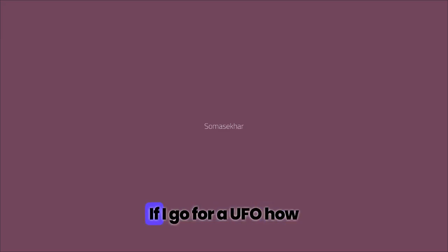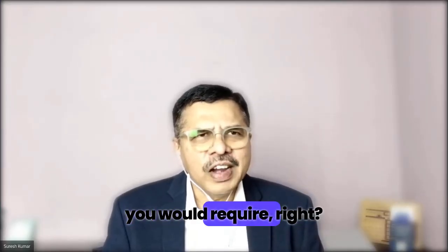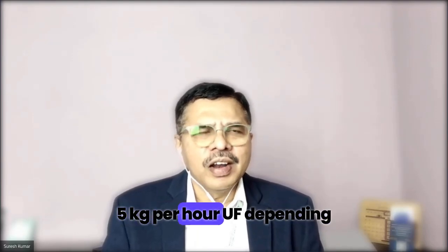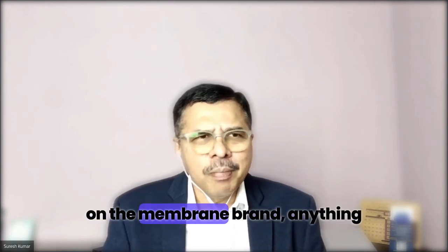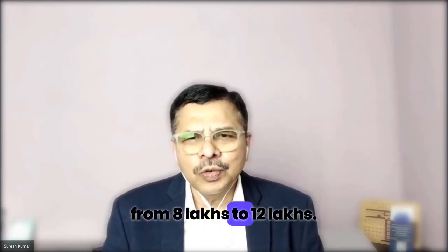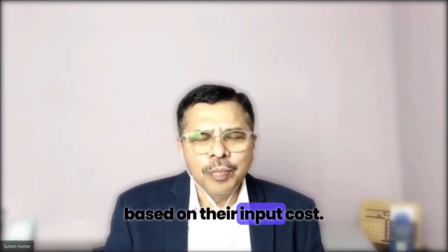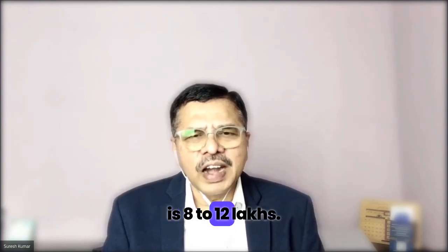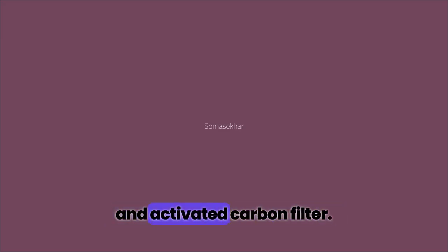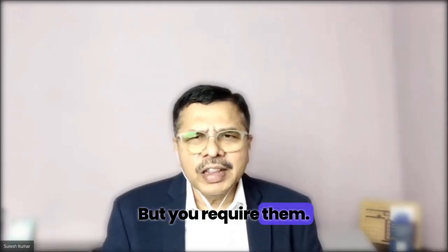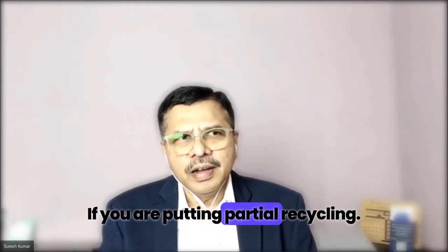In case I go for a UF, how much does it cost for me? Maybe 5 KL per hour UF is what you would require, right? A 5 KL per hour UF, depending on the membrane brand, is anything from 8 lakhs to 12 lakhs. Various manufacturers give you prices based on their input cost, but the ballpark figure is 8 to 12 lakhs. Apart from this, the pressure filter and activated carbon filter you don't actually have to use, but you require them if you are putting partial recycling.